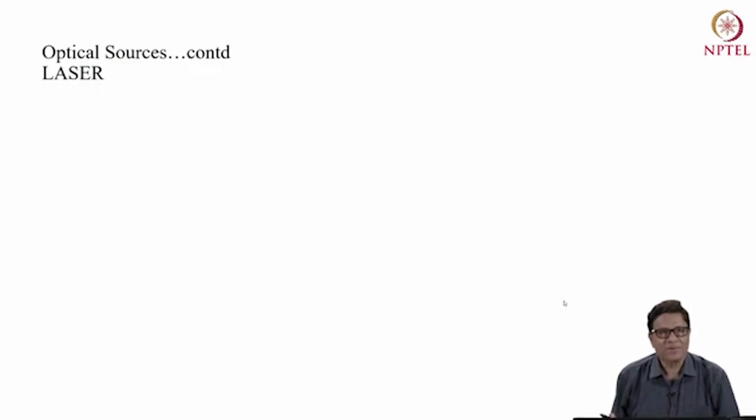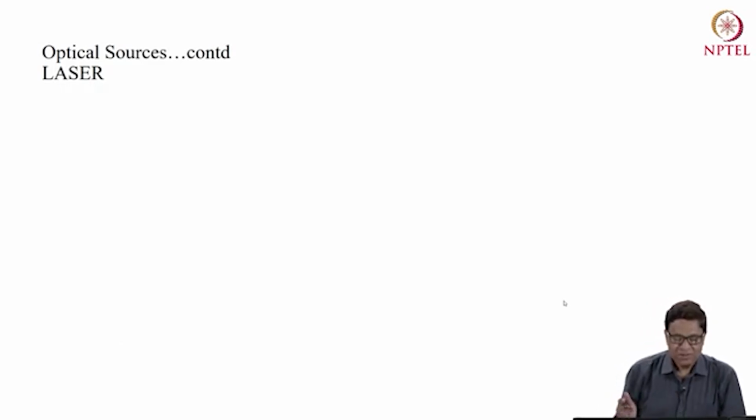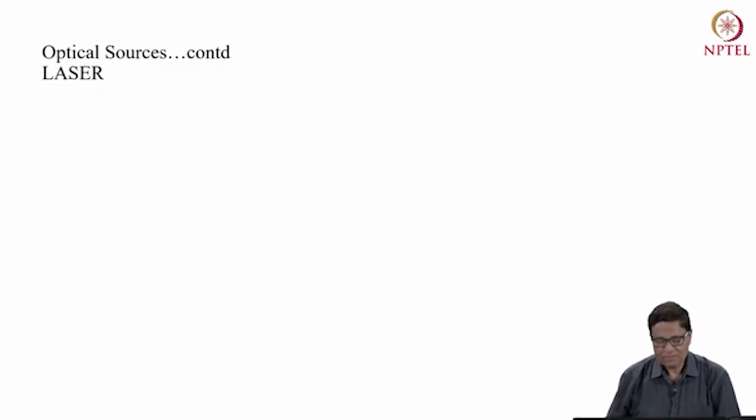We will study how a laser operates, what the typical bandwidth of a laser diode is, and what a modulation bandwidth is, and we will understand different types of laser, the types of noise it produces, and so forth. So let us start our discussion with laser.